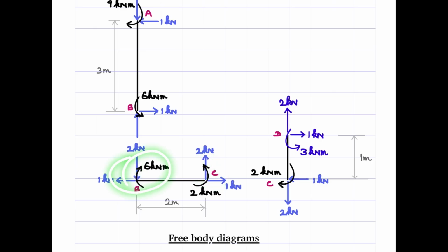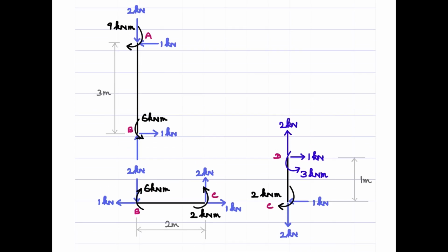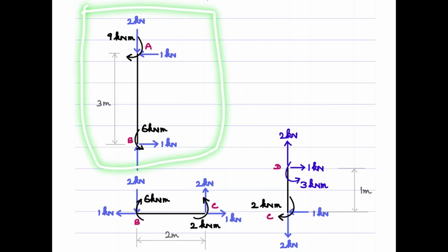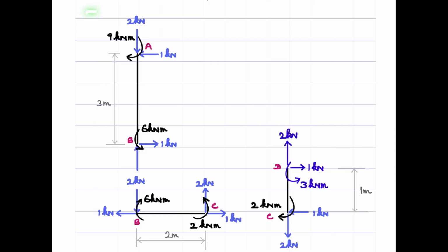And how about this value of the bending moment there? So we see that this 2 kilonewton meter bending moment is already there, and then due to this 2 kilonewton, 2 into 2, 4 plus 2, totally 6 kilonewton meter is there, and this is counterclockwise, right? So in order to equilibrate that, there should be a clockwise 6 kilonewton meter bending moment here. So that's the way we get the values that are required to complete the free body diagram of the member AB as well. When we do that, automatically you determine the support reactions here. Okay, you can do either way.